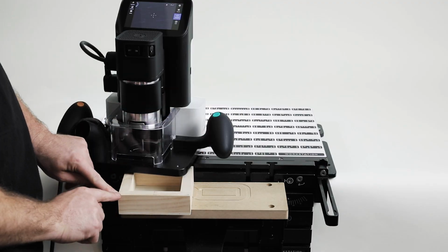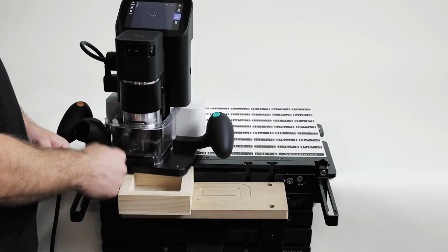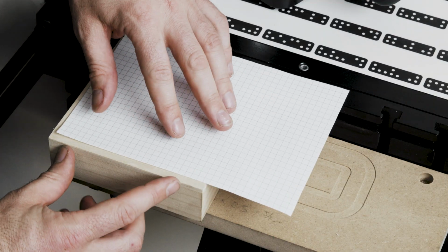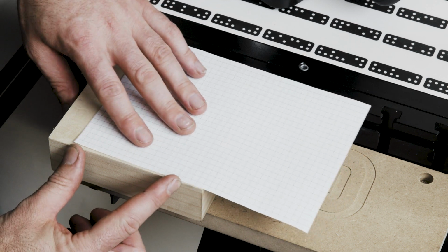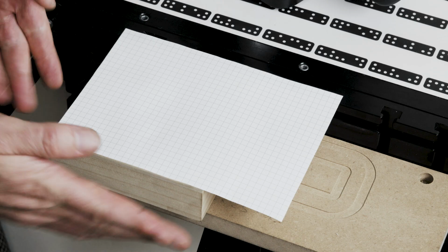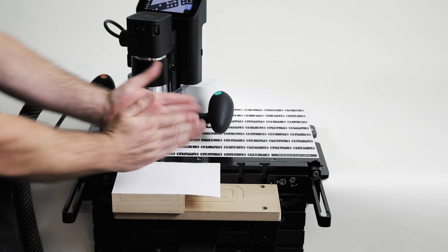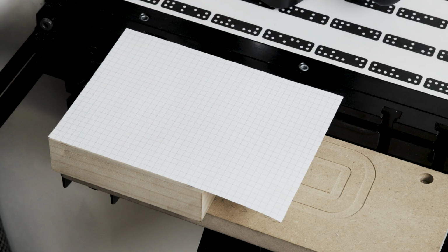We're trying to get a 0 point here with x parallel to this edge, running right along that edge, and y running along this edge. So it's basically just like applying grid paper to the corner of your object. Probe 1, probe 2, and then probe 3 for a perfectly aligned grid. That enables us to place things in the right orientation and specific increments from each edge very easily.